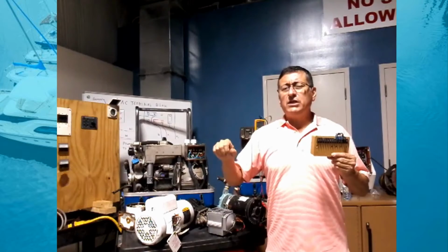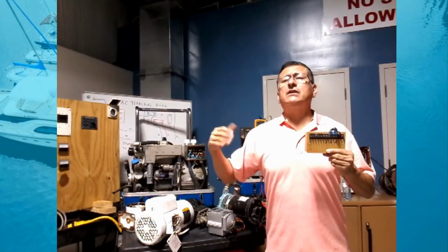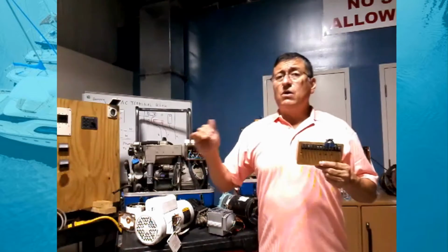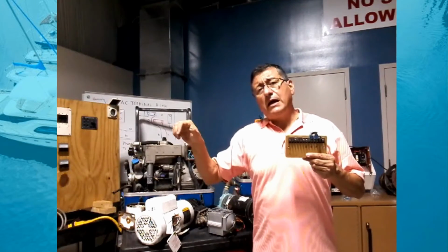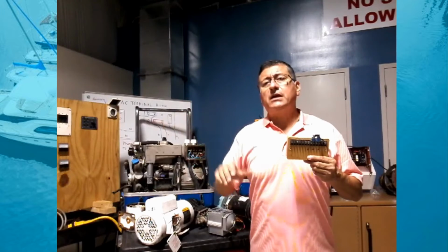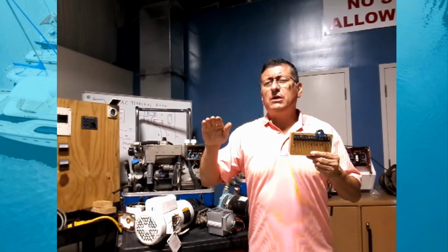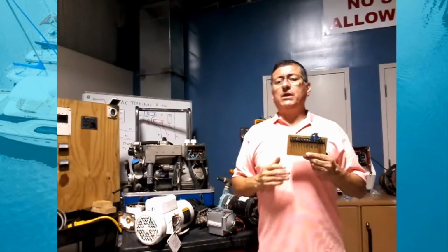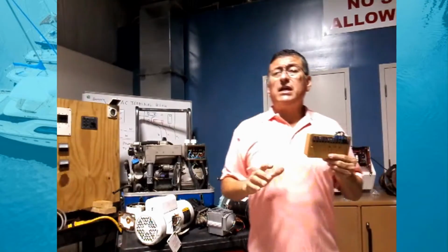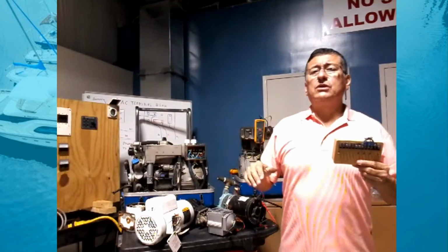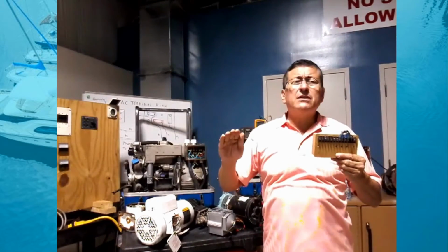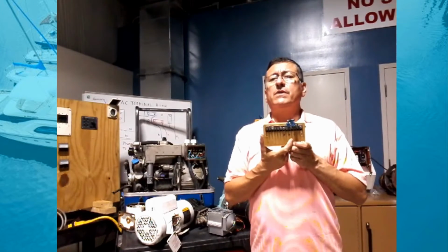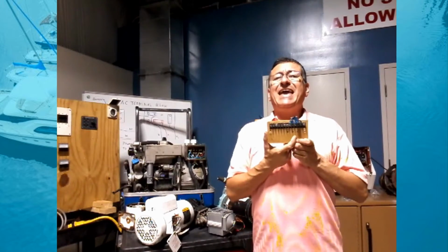You apply the load, the generator decreases the RPMs and immediately recovers the RPMs. In some cases, when the load is too heavy, when you apply the load on the breaker, you hear the RPM decrease and recover. If the generator, when you apply heavy loads, takes more time than recommended to recover the RPMs, you need to adjust the third button, the third spot, gain.